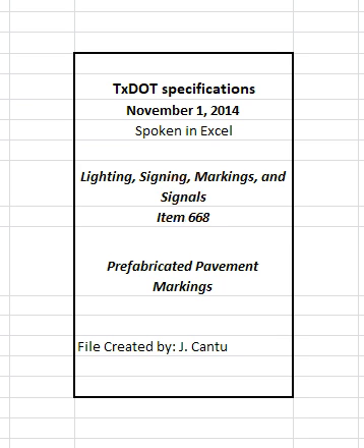3.3 Dimensions. Place markings in accordance with the color, length, width, shape, and configuration shown on the plans. Locate alignment as shown on the plans or as directed. 3.4 Methods. Place all materials in accordance with the material manufacturer's instructions, as well as the surface condition, moisture, and temperature requirements of this item, unless otherwise directed.